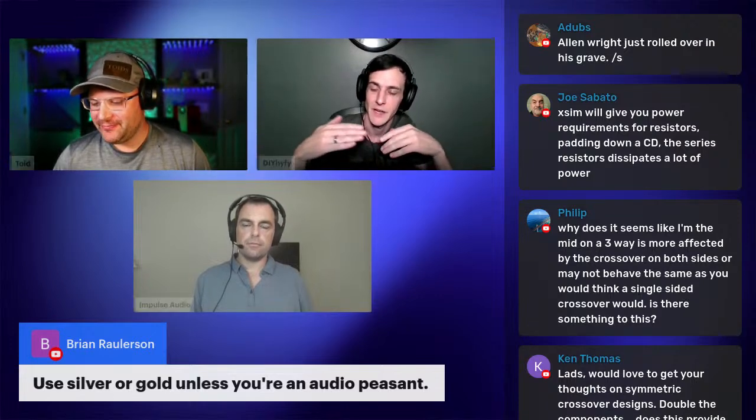As we adjust those values, we can lower or attenuate our tweeter's response, or even shape it. The series resistor will shape, so that can roll off your top end and lower end. So be careful as you play with those values. Watch your response. If your response starts to look like a sad face, then something is going on.